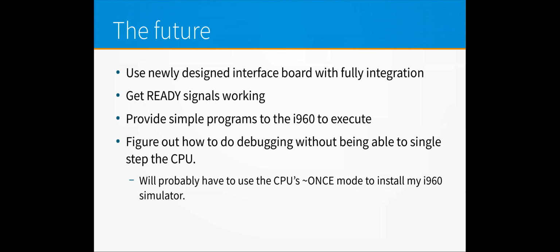It's using something called an Adafruit Grand Central M4. But I put that on hold because I figured out how to keep going with the ready signals. The CPU also provides something called ONCE mode, so you can hook into the bus and it tri-states things. It was confusing, but I now have some ways to move forward if I need to debug in the future, though I'm not worried about it right now.